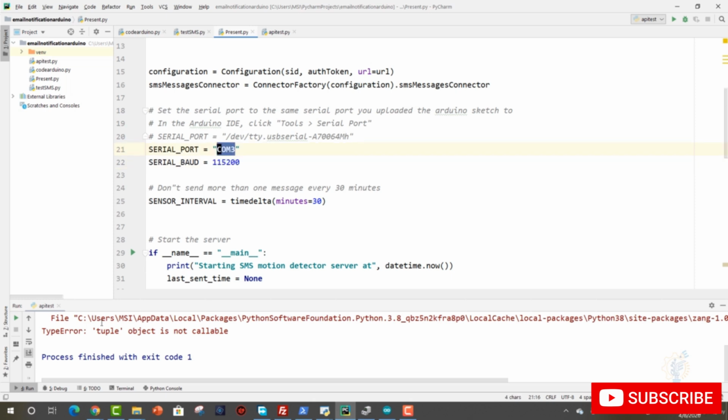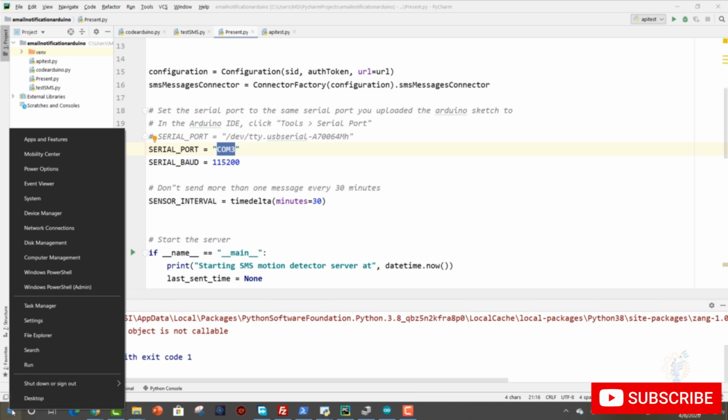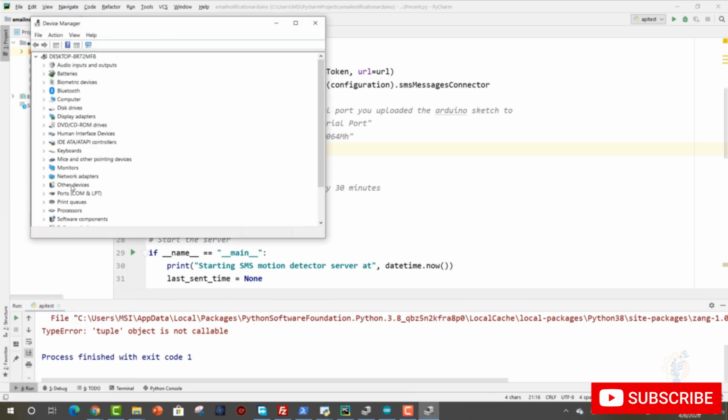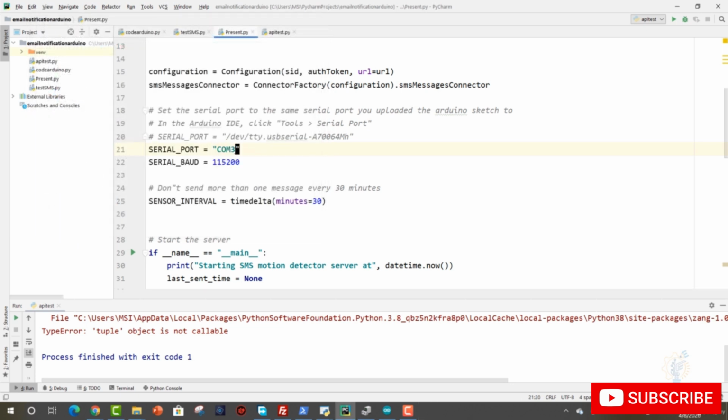Regarding the serial port, you have to go to the device manager by right-clicking your start menu, clicking device manager, and from here checking the ports, and you can see it's COM3. I have an Arduino Uno connected to COM3. Now as you can see, this is our COM3. You can change it to whatever you have in your device manager.